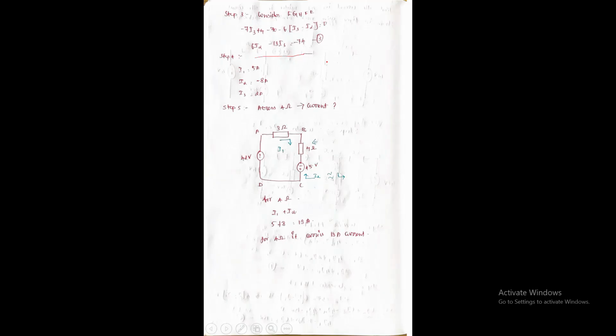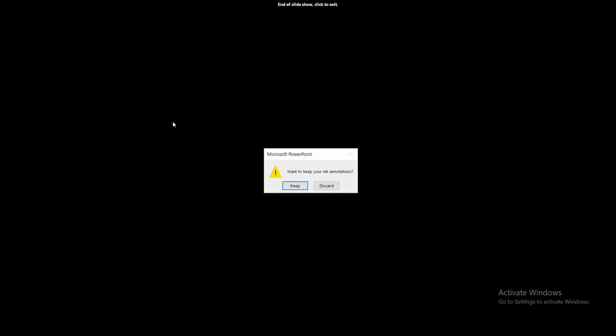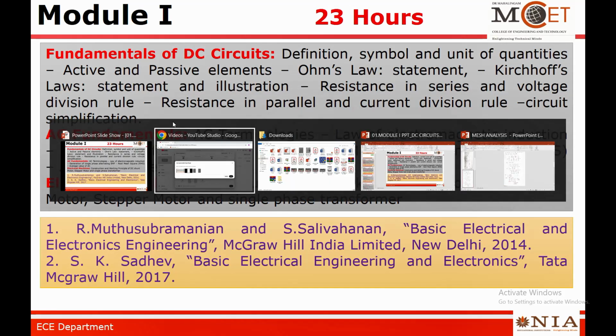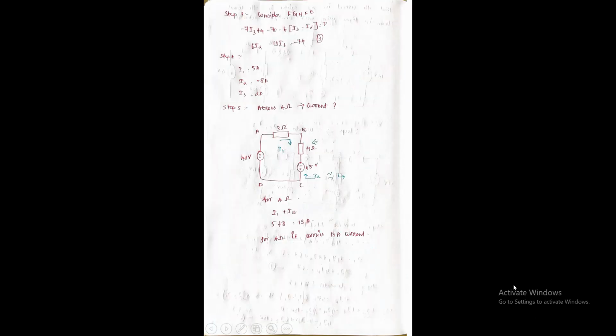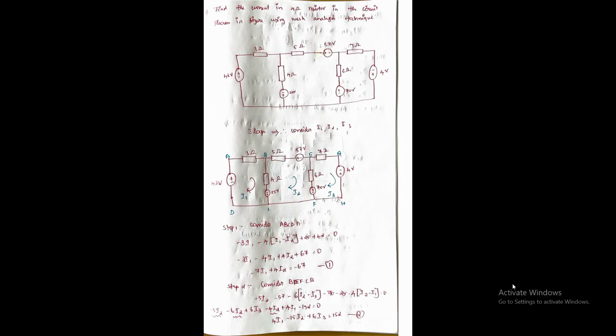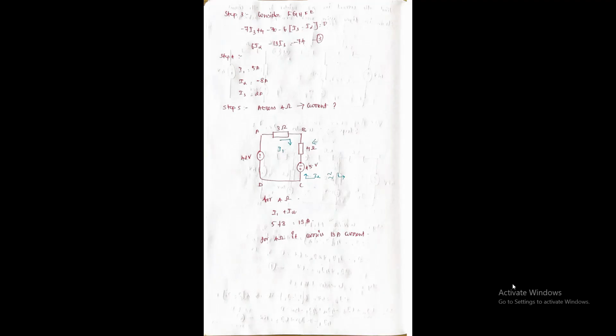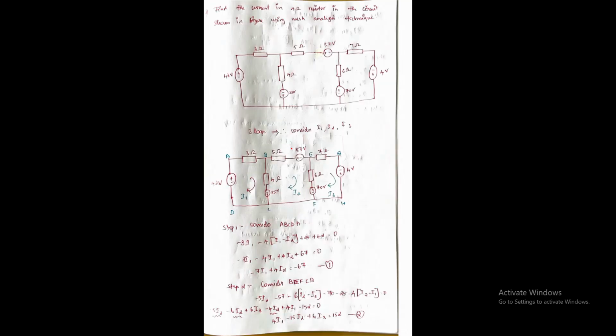So again, by using the calculator, we are going to find the values for I1, I2 and I3. So go to the calculator and give the unknowns as what? 3 unknowns. Here we have 3 equations. So equation number 1, 2 and 3 have 3 unknown values, I1, I2 and I3. So choose the unknown value as 3 and enter those equations as obtained here.